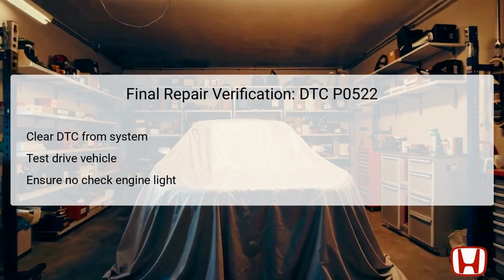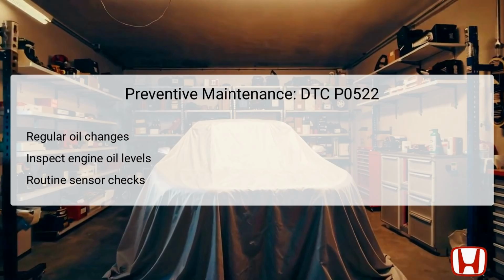This trial run allows the technician to observe whether the check engine light re-illuminates, which would signal that the issue may still be unresolved. During this test drive, it's also important to monitor the engine's performance for any irregularities. Successful failure-free operation confirms that the issue has been rectified and that the engine oil pressure sensor circuit is now functioning as intended. To prevent future occurrences of DTC P0522, regular preventive maintenance of the engine is vital.